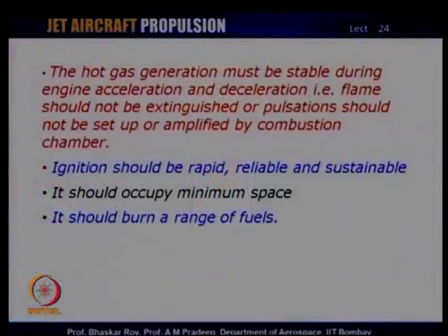The whole engine would burst like a little bomb, and this is something which must be avoided under all considerations and under all operating conditions. So, the combustion chamber designer needs to ensure that none of these catastrophic things ever happen during the operation of the engine. The other requirement which the combustion chamber designer needs to conform to is that the ignition should be rapid, reliable and sustainable.